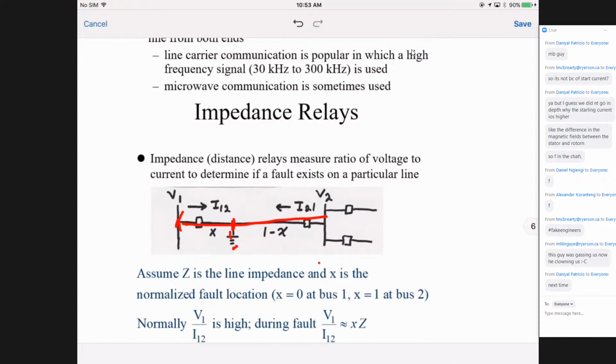So you rely on the impedance relay, and you can identify where the fault is much better than just searching, because the line is sometimes across some valley or hill and may not be easily accessible. And you want to return the service as quickly as possible.